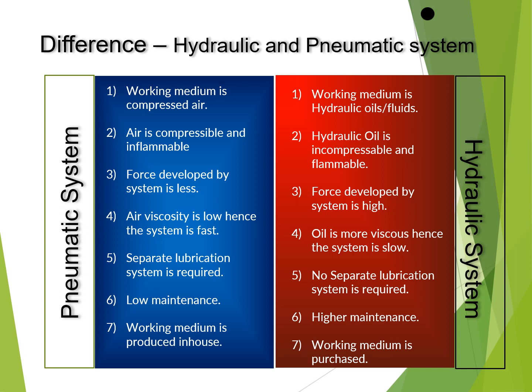A separate lubrication system is required. If we recall, in the FRL unit, we studied it. In a hydraulic system, we do not need any separate lubrication system because we are using the hydraulic oil as the working medium. A pneumatic system is a low maintenance system, whereas the hydraulic system has a higher maintenance cost.